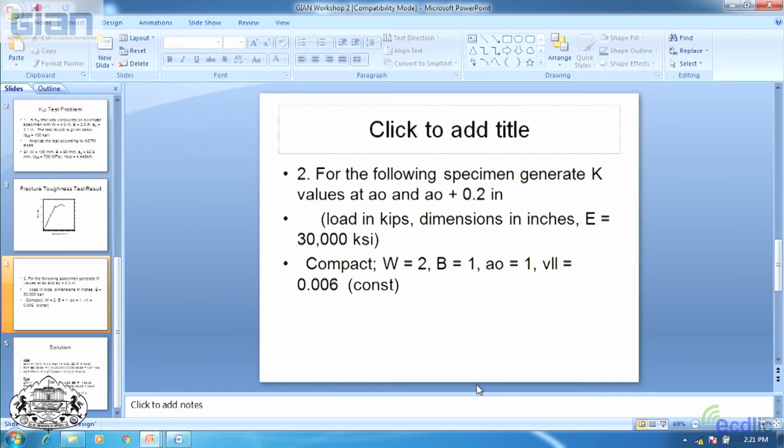and the V, that stands for load line. You can imagine that plot over there, this thing, the displacement depends on where you place the gauge. If you place the gauge far from the crack tip, you get a different value than if you place it close to the crack tip. The table in the handout, BEV over P, that you have is for load lines. It doesn't say that, but that's what it's for. And very often people put the gauge on the load line. You'll see how you can do that in next week's lecture.